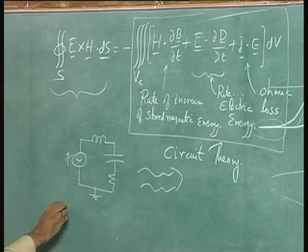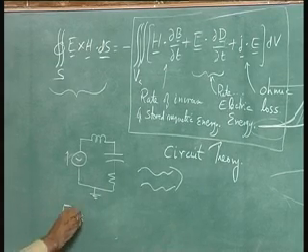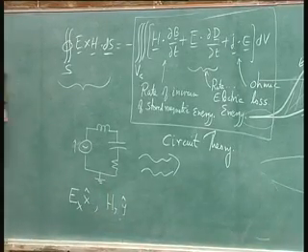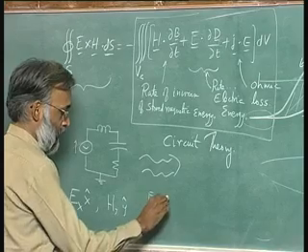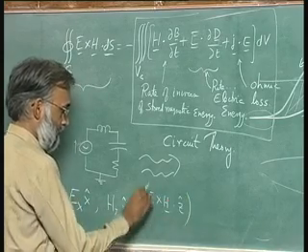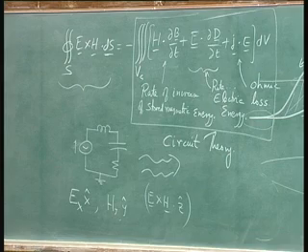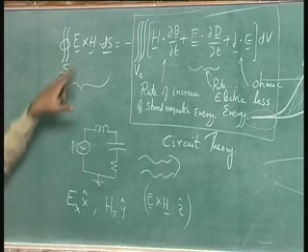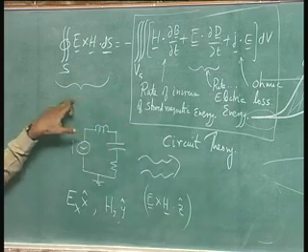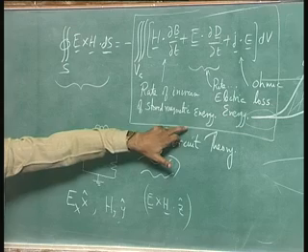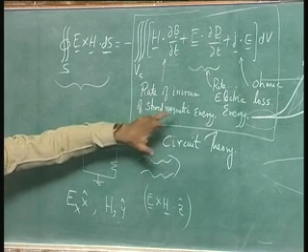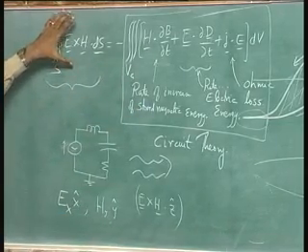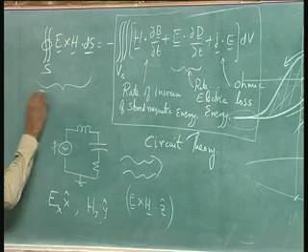As you saw, we had Ex, x hat, Hy, y hat, which meant you have E cross H dot z hat, and this is not 0. Once you have this kind of possibility, then there is something new that is coming into electricity and magnetism, something that is not there in circuit theory, something that your KVL and KCL cannot capture, and it is this piece that is the crucial new piece which we call radiation.